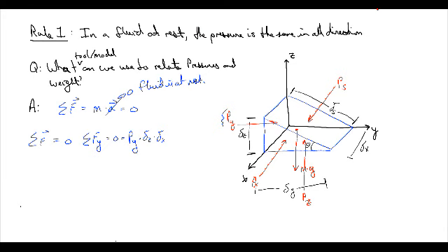And then there's going to be a negative force in the y direction, which is going to be Ps times delta s delta x, which is this area here. Let me draw it in green. This area here. But we only want the y component of that, right? So if we only want the y component of that, we have to multiply it by the sine of theta.